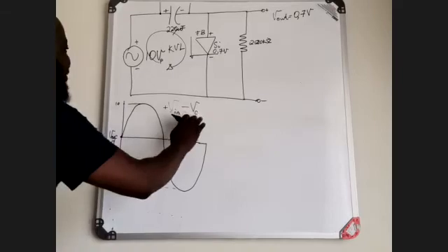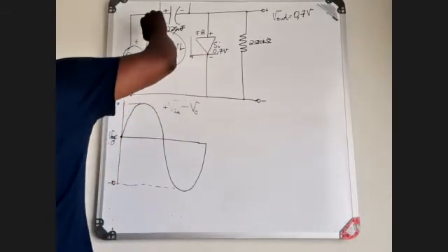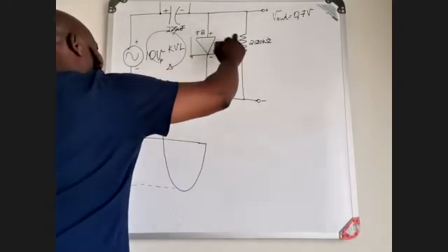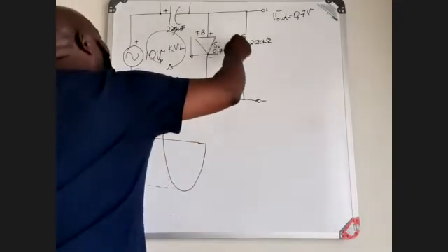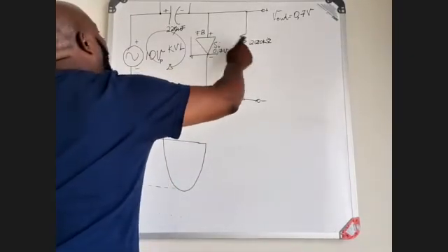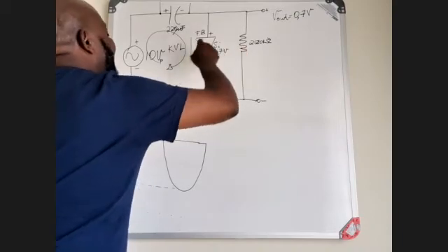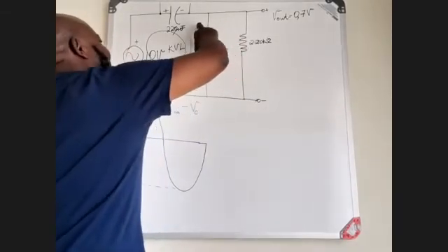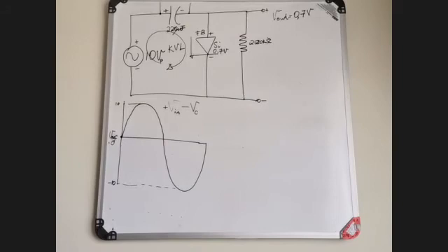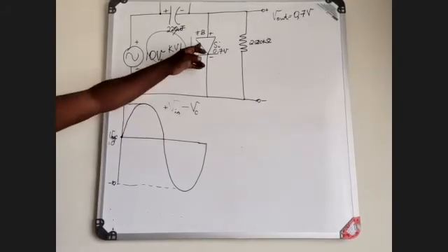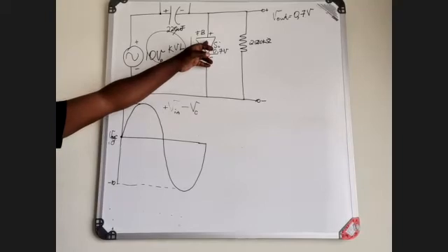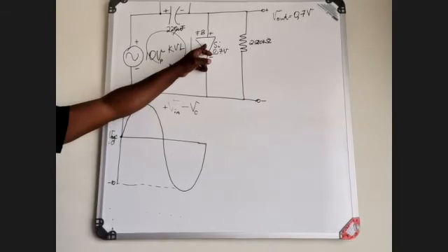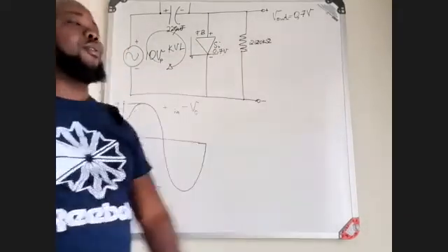Now, if that is minus V of the capacitor, then when you continue, remember these two components. I just want you to bear in mind, these two components are parallel to each other, which means whatever voltage that I see here is the same voltage that I see there. Because of the magnitude of this and your barrier potential, this voltage is already bigger than that one, which means that component is going to switch on. And if it switches on, it's 0.7 volts.